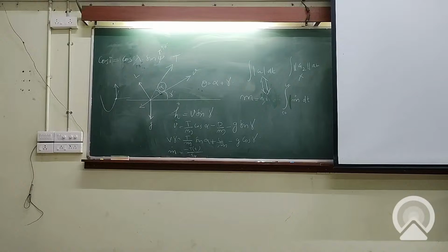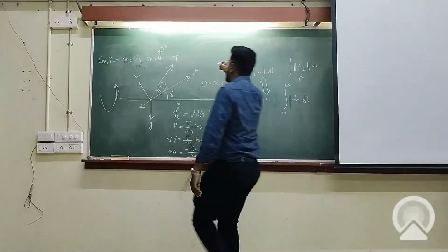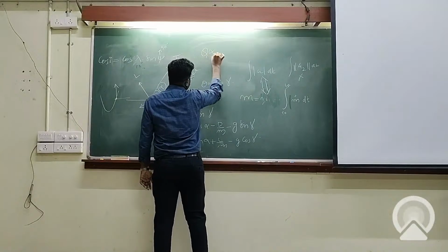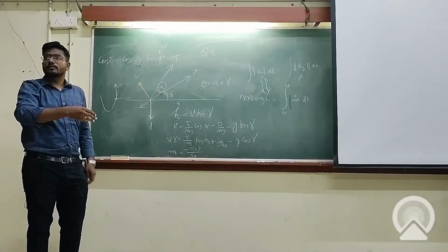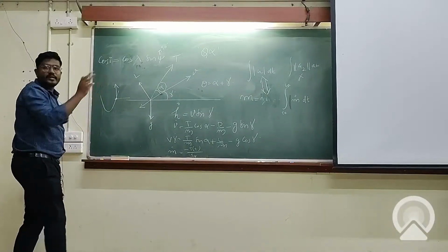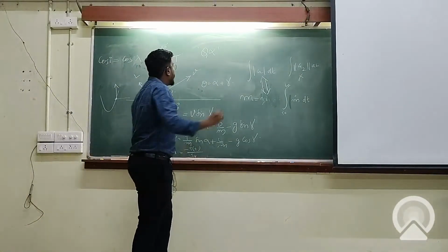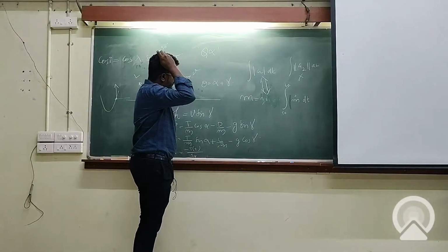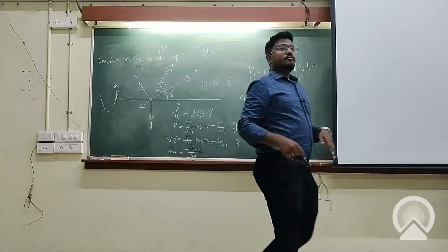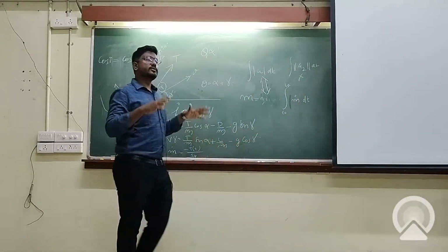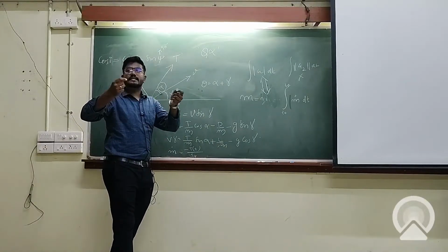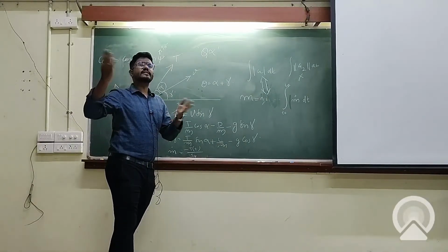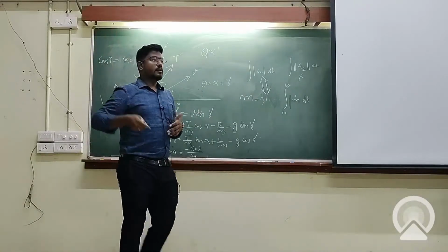They throttle down so that, basically, what is structural load? The constraint can be represented as Q alpha. Right? Q is half rho v square, the dynamic pressure, and alpha is the angle of attack. By throttling down the vehicle, what you are actually doing is reducing the dynamic pressure when the density is significant. After that, you can throttle up and go ahead.